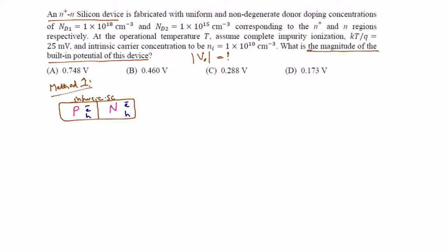So for current to flow, electrons have to move from one side to the other, as well as from the other side to this side. At that time they either have to gain energy to get excited, or they have to lose energy to move from one side to the other. In forward bias, it requires external energy to move from one side to the other, that is climbing. In reverse bias, they will dissipate energy as they move from one side to the other.